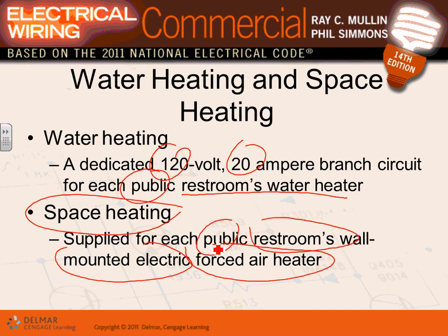There are two types of hot water carried in any building. Something called domestic hot water, that's for you and I to shower with and wash our hands. The other one is for heating the building: hot water, closed loop hot water. They use it to heat the building. Everybody understand? It took me a while to understand the difference. These are two different piping systems. They don't interfere with each other.